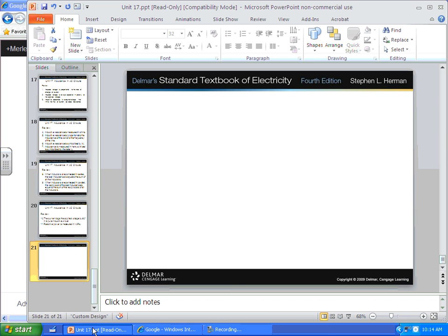A perfectly tuned circuit has a 0-degree angle, or very close to it. And what is the power factor for something at 0 degrees? 100%, right? The cosine of that angle, I shouldn't be telling you this so early, but the cosine of the angle is the power factor. How much power is going to be converted from input power to watts, cranking force, in the case of a motor.